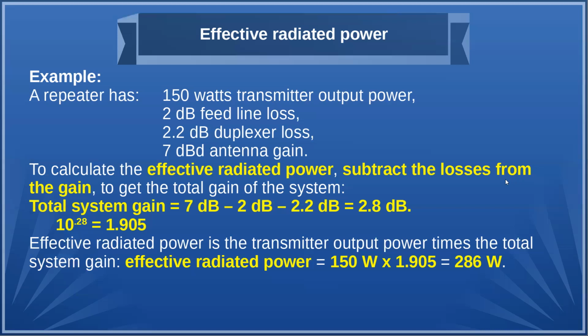Well, I don't need any of that math because I got 150 watts and the end result is 2.8 dB, which is close to 3 dB, and 3 dB doubles the power, so 150 doubling is 300. But if you're a perfectionist, then you do it the other way with your calculator. Or just look in the book. Just use your watt meter.